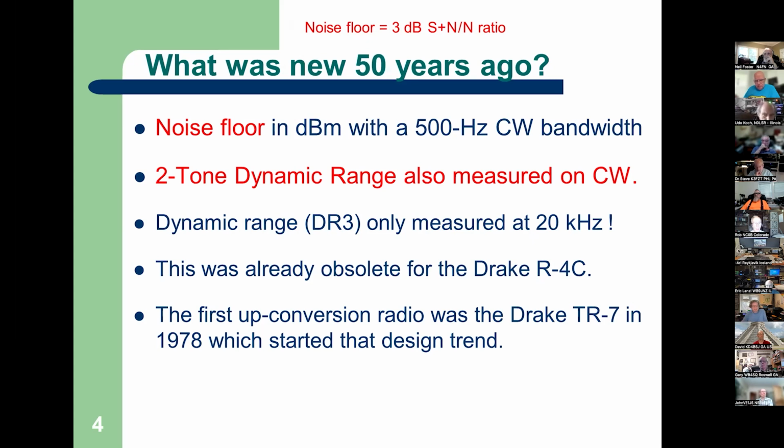of the radio. But the trouble was the testing at that point, 1975, was only done with two signal generators 20 kilohertz apart. And if you're saying, is that going to approximate CQ worldwide or a DXpedition? No, because the QRM isn't 20 kilohertz away and 40 kilohertz away. It's close in.